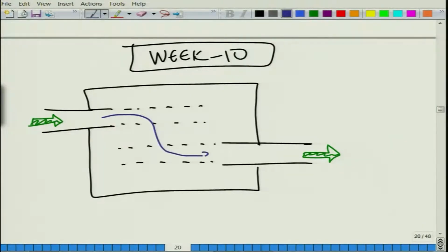I am drawing here a cross flow perforated element which is open ended, something like this. So, here the waves have really no choice but to go through these perforates and pass through these 2 perforated pipes 1 and 2 and then leave this outlet pipe. So, this is the inlet and this is your outlet version. So, the waves have to go like this.